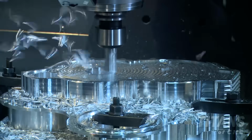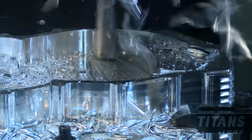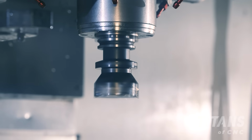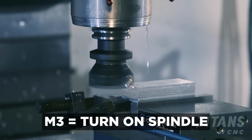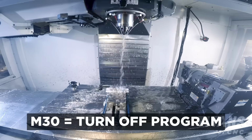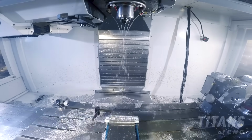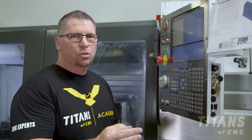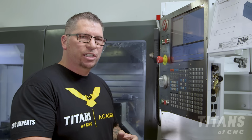G codes actually create action. It makes the machines move. M codes usually turn things on or off. So to turn on the spindle, you'd hit M3, spindle turns on. Turn on the coolant, M8, shut off the program, M30, stop a sub, M99, and on and on. So G codes create movement, M codes turn things off and turn things on.